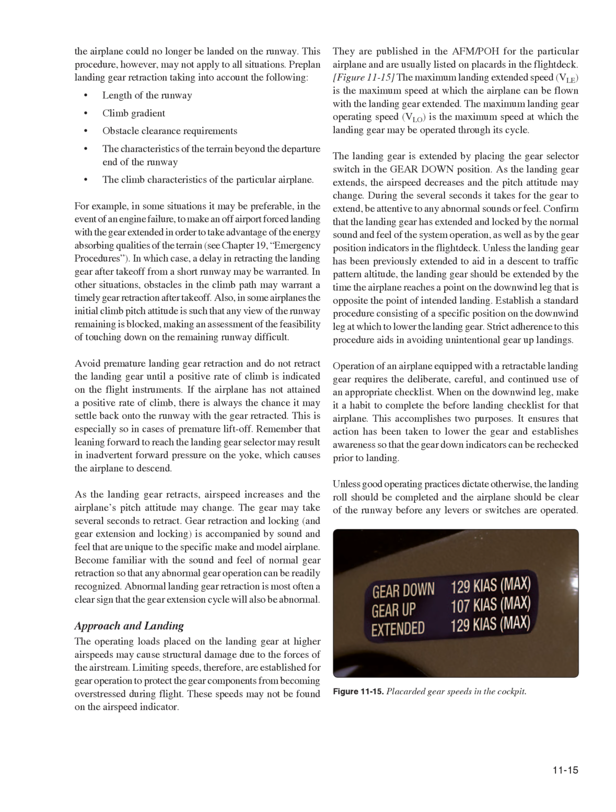Remember that leaning forward to reach the landing gear selector may result in inadvertent forward pressure on the yoke, which causes the airplane to descend. As the landing gear retracts, airspeed increases and the airplane's pitch attitude may change. The gear may take several seconds to retract.